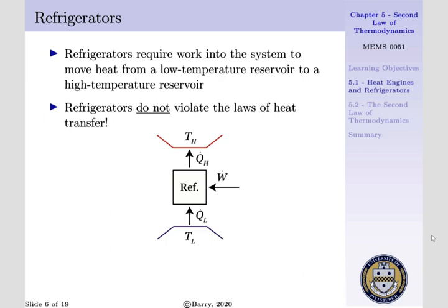Thus, refrigerators do not violate the laws of heat transfer that we have previously defined in this course. We've previously said that heat has to transfer from a high temperature to a low temperature reservoir, and that the reverse is not possible. Now we note that we have to put work into the system to circulate our refrigerant such that it is able to transfer heat from a low temperature reservoir to a high temperature reservoir.